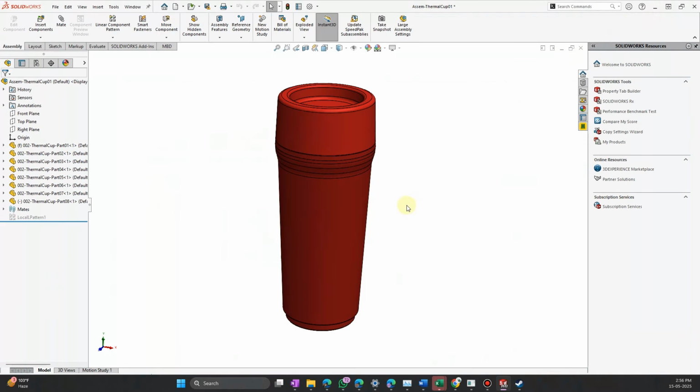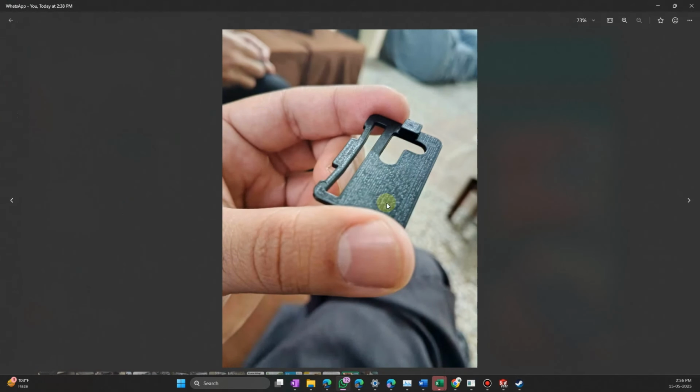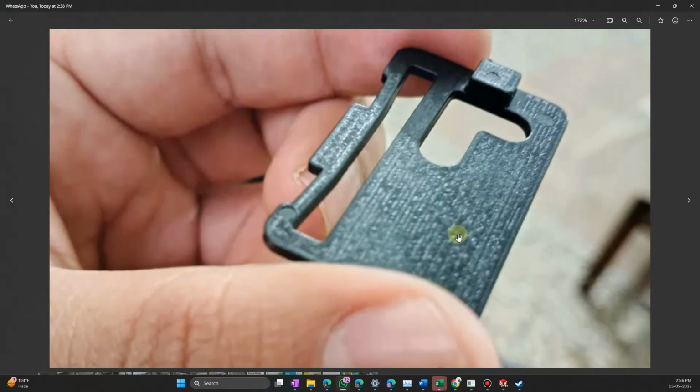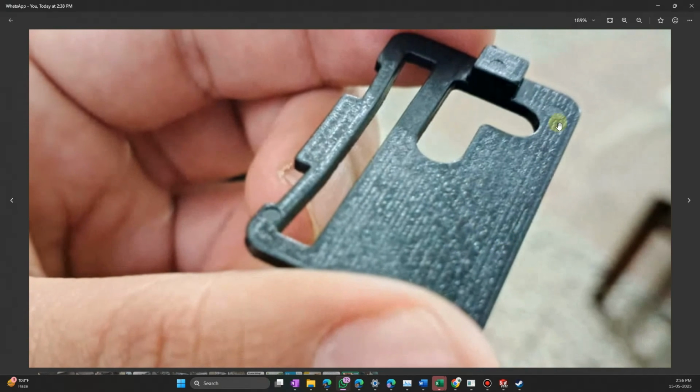There's another thing that we have to keep in mind, that the internal components, which of course have all surface B, which are never going to be exposed to the user, can have a rough surface finish. As an example, I'm going to show you a part which is an internal component in a mechanism. You can see that this part seems to be 3D printed with a very rough surface, but you can see the ejection pin marks on it, which means this is injection molded, but still has a very rough surface finish because we really didn't want a good surface finish here.